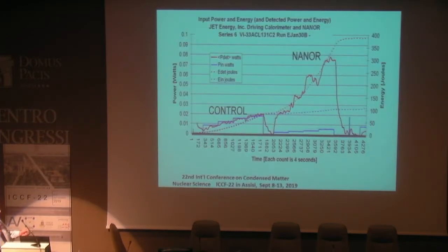We can see the same for full bore calorimetry, as we see here, where we do one other thing, of course, which is we do the time integral. You should always do a time integral because you can pick up phase change, you can pick up errors. So here, for example, we see for the ohmic control, we get out what we put in, and here's the energies.